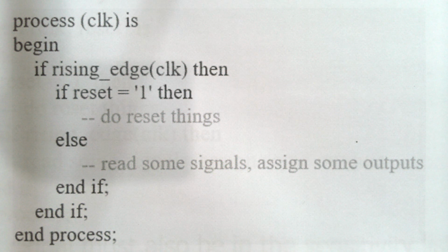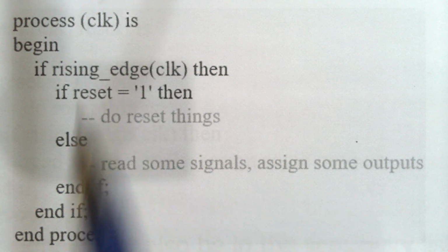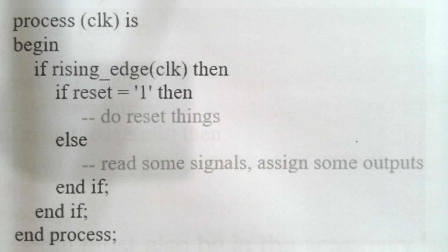The reason being, and you will ask why we only need to put CLK in the sensitivity list. It is because everything else is looked at when the clock changes. So because we have the clock in a sensitivity list, when that clock changes, everything that's aligned with the clock signal, the clock port, is also looked at.